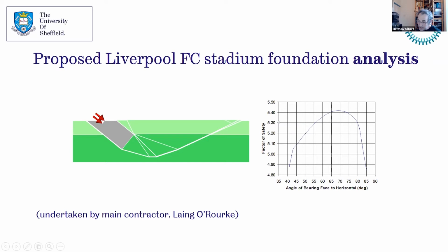And they were able to quickly establish that by increasing the angle, the foundation would still be safe. So this is an example of a mid-range analysis tool, in this case using the discontinuity layout optimization technology, which I'll talk about later, to give good solutions in a very short time frame.